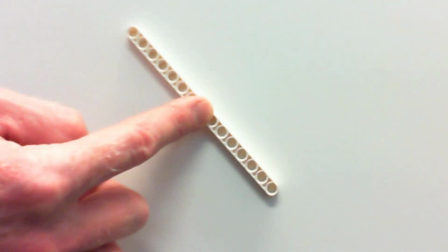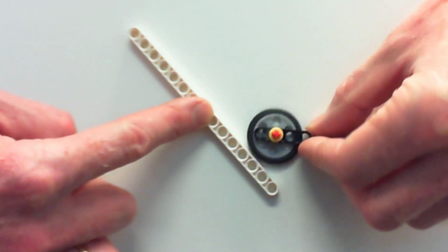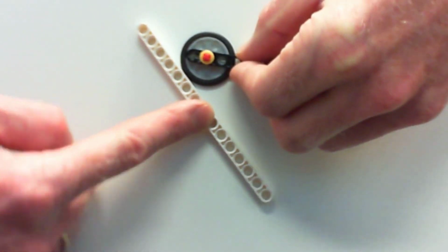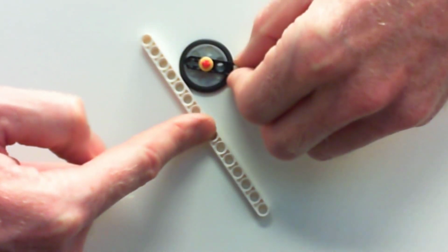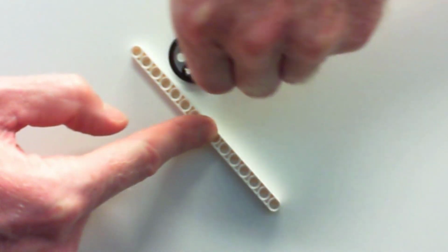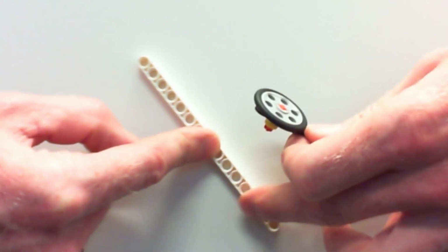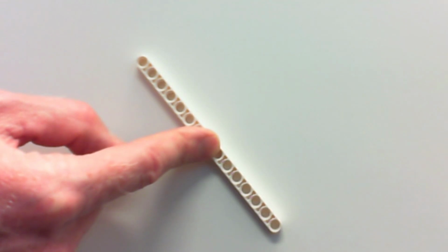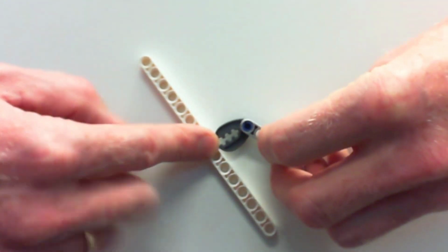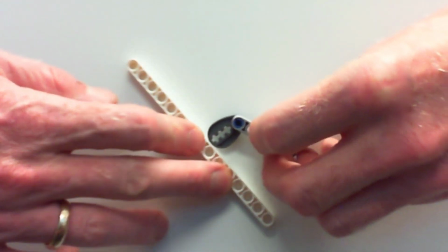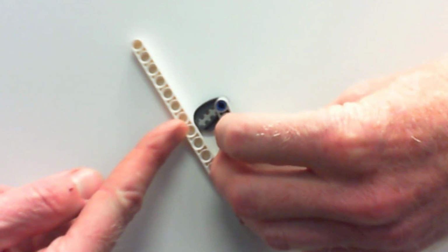If I have a different kind of body interacting, let's say that I have this roller here, I still end up with that perpendicular force, always perpendicular to the surface. So it doesn't matter at what angle this wheel is coming in, I end up with a force that's perpendicular to the white piece right here. It's also true for a rocker. So here is a rocker.